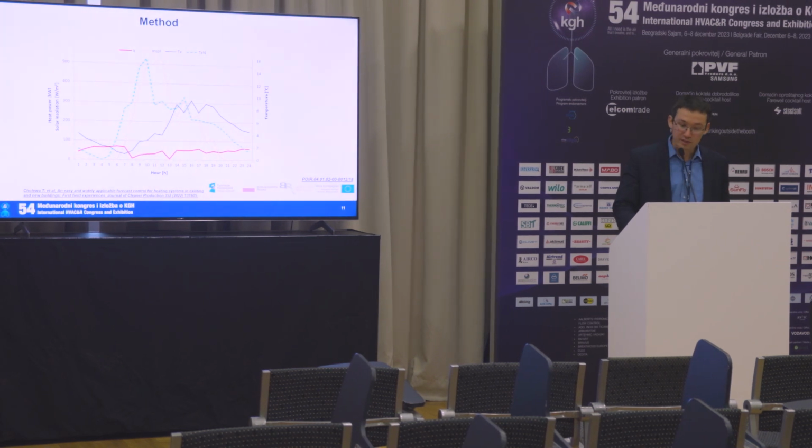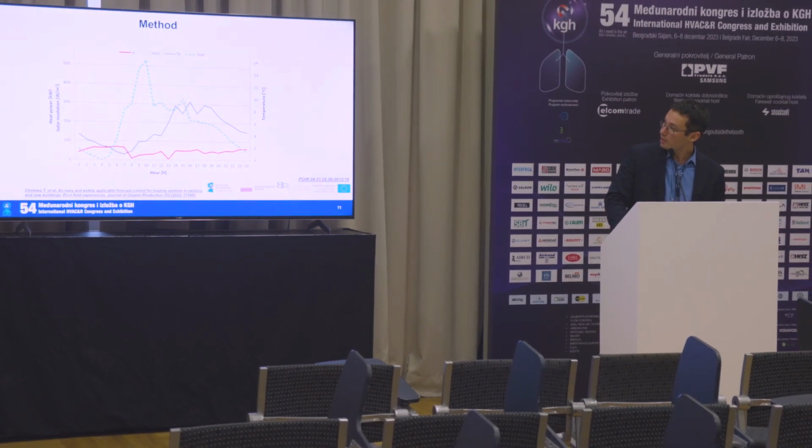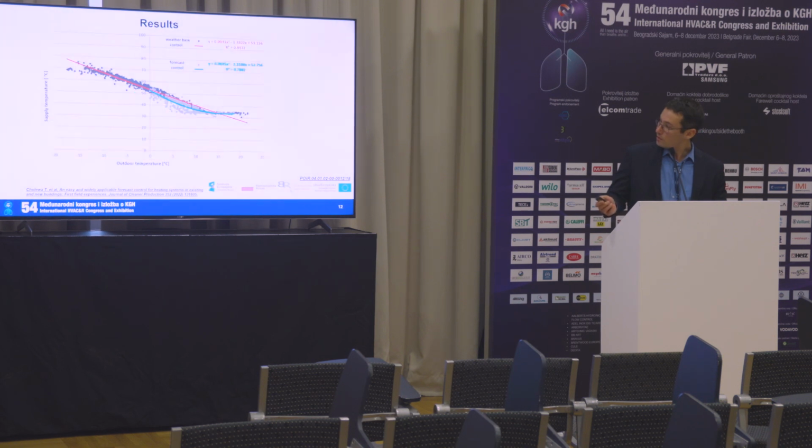So here is some kind of example. We can see this black line, it is outdoor temperature, red line is power consumption. So we implemented this blue settings of outdoor temperature, and based on the coming solar radiation, yellow line. So based on this, we react on the building required energy needs in advance, and we decrease already the power consumption. This reduces, as you see, the supply temperature in a heating system.